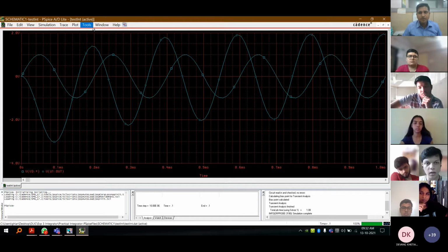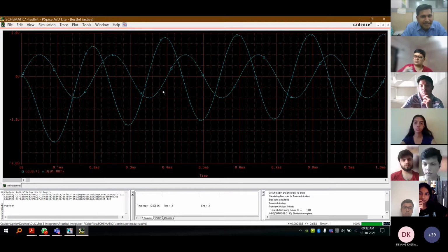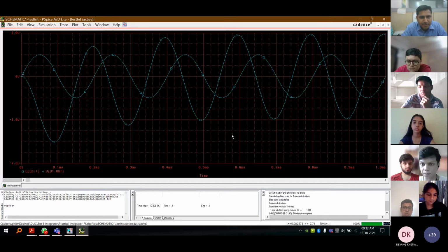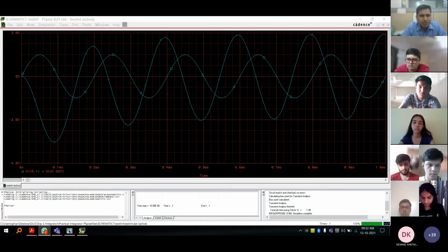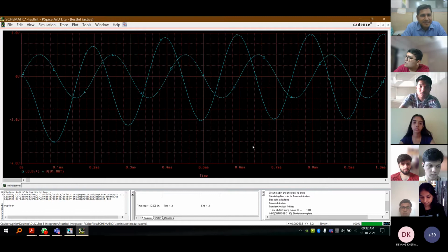Now, one key thing that you guys need to know. So what you said is exactly right. I want you to test the slew rates for these particular op-amps. When you're looking at TL084, when you're looking at 741, and when you're looking at OP07, you'll observe this slew rate response being completely different, and because of which the phase being completely different when you're testing it with the 3 op-amps. Right? Yeah, go ahead, Rishi, please.